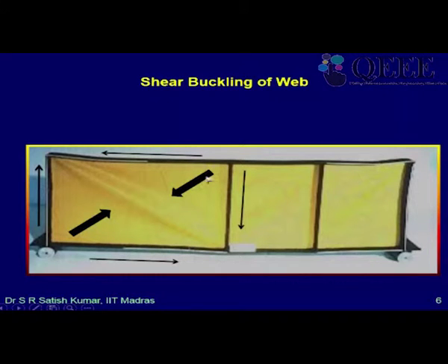So for equilibrium of this element, you end up getting complementary shear, and under the action of the vertical and the complementary horizontal shear, you find that one diagonal, this vertical force has a component along this diagonal. Similarly, this horizontal force has a component along this diagonal. So the two add up and you get one diagonal under compression, the other diagonal under tension, right? So this same force will have a component; if I draw it like this, I'll have a component which will be pulling it away and downwards. So those are the two components of this vector. Okay. So the other diagonal goes in tension.